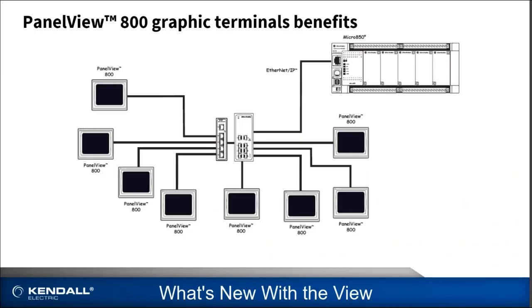And the Panaview 800s work great for large, simple machines. I have a number of customers that make really big equipment, but they're very simple in nature. But you want to have multiple points where operators can start and stop equipment, or they can see faults and other warnings on the machines. And using the Ethernet protocol, we can communicate up to 8 of them with a micro 850 controller, and it works really well.